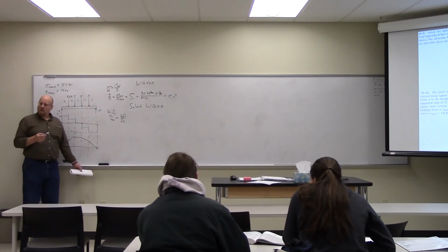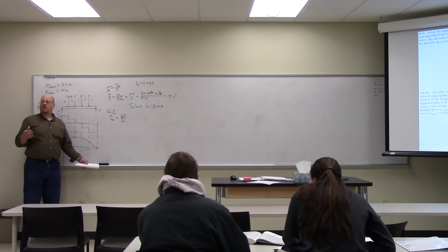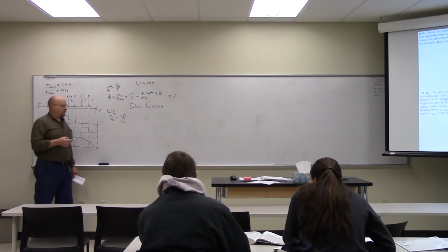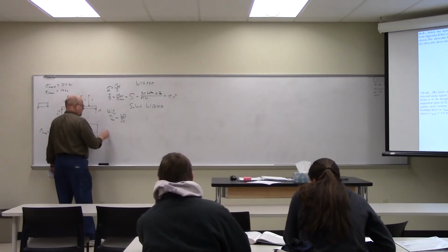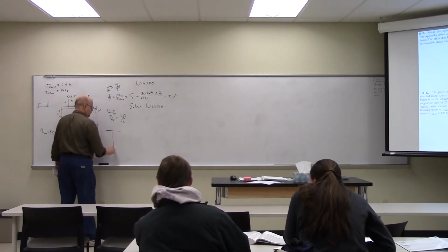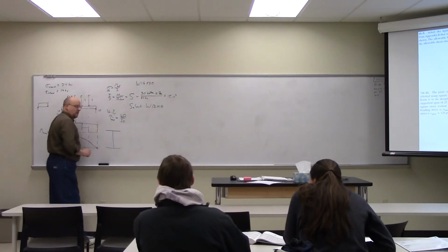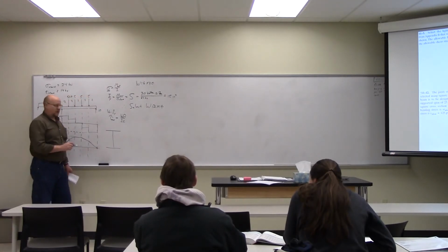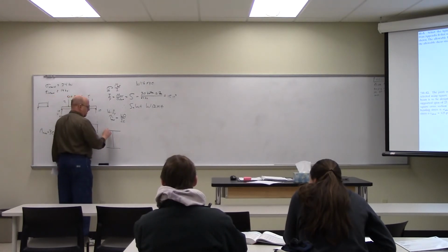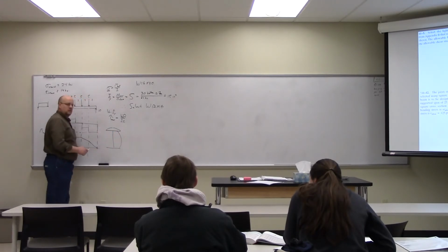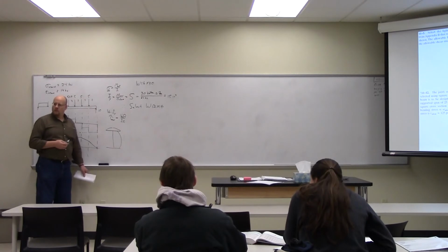It turns out that in many engineering applications, they allow you to make an approximation. If you remember how we did the shear stress distribution on the I-beam, we talked about this last time. It's sort of a parabolic thing that comes up from the ends, the shear stress here, and then in the center it does this. Everybody remember that?